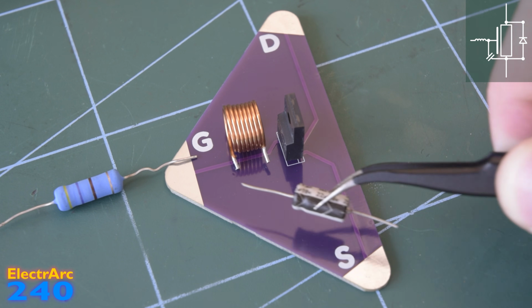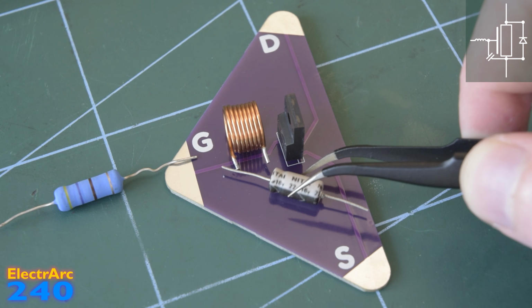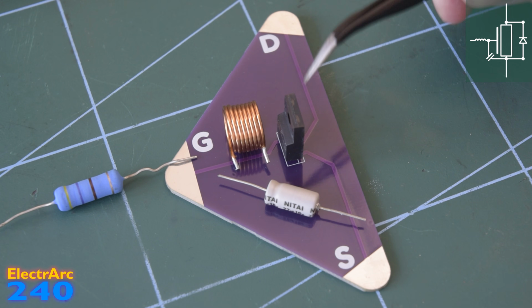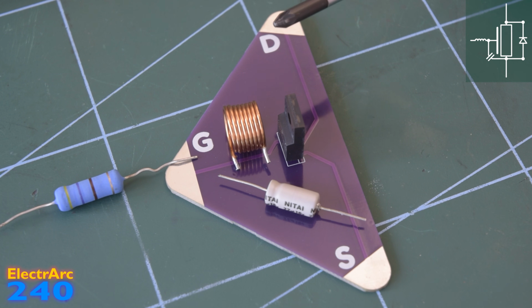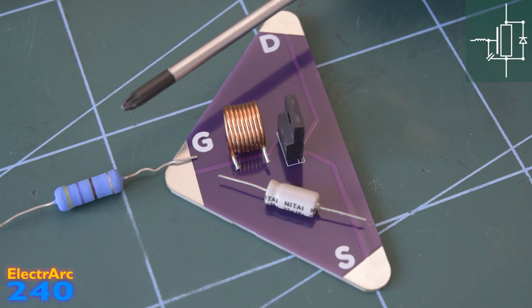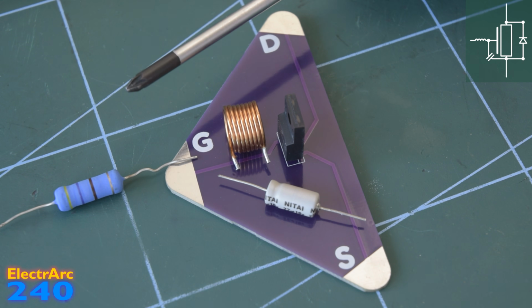Another similar problem is that when combined with the gate source capacitance, this inductance can form an LC tank, which causes oscillations in the gate voltage. These oscillations can cause the gate voltage to exceed the threshold after you've turned the MOSFET off, which will obviously turn the MOSFET back on, or at least partially back on, when you don't want it to, which is really bad. And the overshoots caused during turn on can actually exceed the maximum rating for the gate source voltage and permanently destroy the MOSFET.